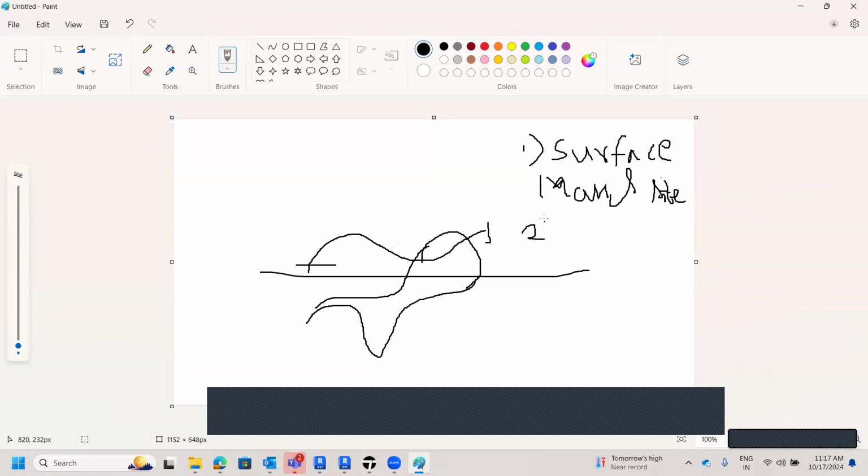So once you do this, your structure would get ready, right? Then you need to divide that structure into surfaces. Divide the surface into divisions, right? And the third step would be, without closing it, you are going to use the adaptive family option and create a component.